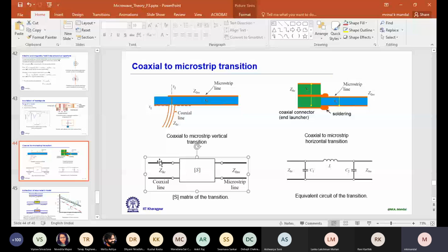So it will give you some change in magnitude and change in phase, but you are not interested in it. You are interested to measure test parameter of your device. Then what we need to do? We need to nullify their effect. So if you want to nullify their effect, you have to first know what are the S parameters of this adapter itself. Okay. So if you know that, then actually we can do error calculation.